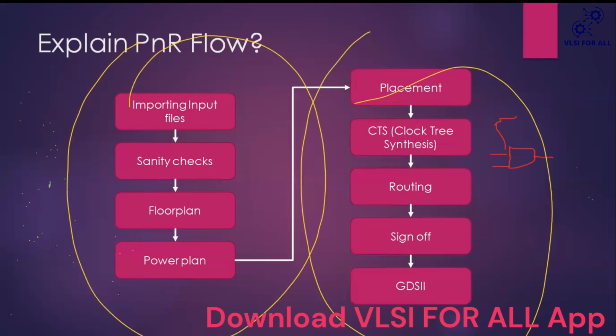This is the major stage, where we have to spend major time on the routing. CTS is very critical, not critical, like we have to give more priority to CTS, because the entire design timing will depend only on the clock. For that we need to take some extra time to do routing for the clock trees.